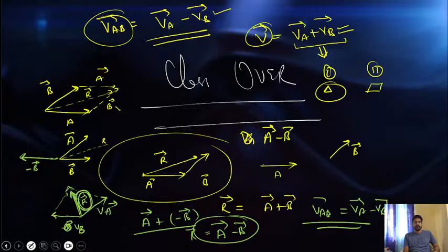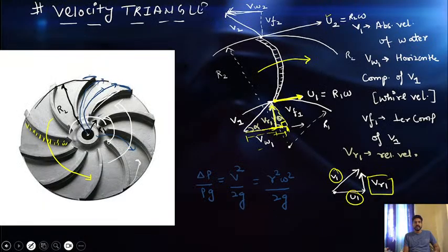If we are talking about the centrifugal pump, then for the centrifugal pump there are two things. First thing is that this alpha is actually 90 degree, guys. What is the meaning of 90 degree? It means that my V1 is striking the blade perpendicularly. I hope that you remember that animation in which water is perpendicularly striking the blade. So this alpha is my 90 degree.